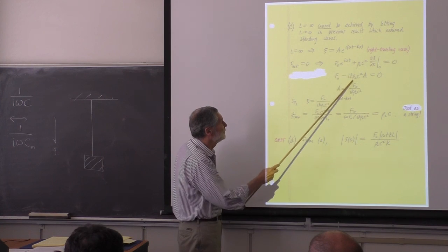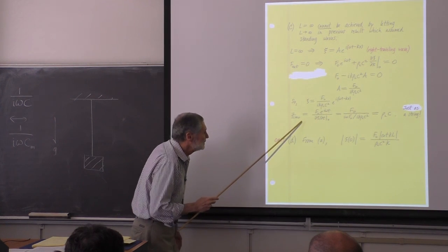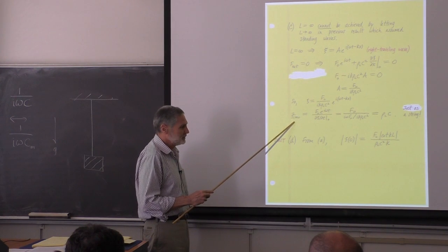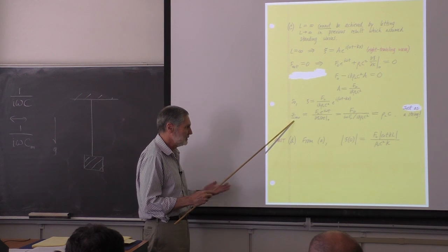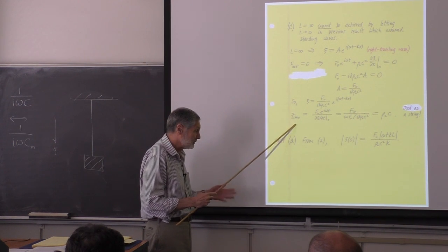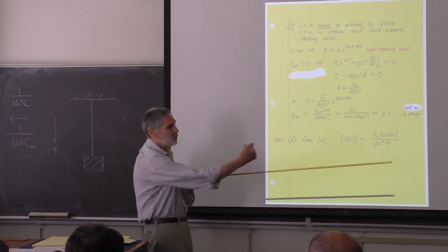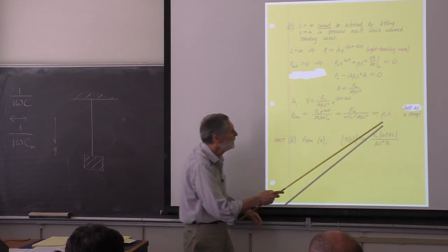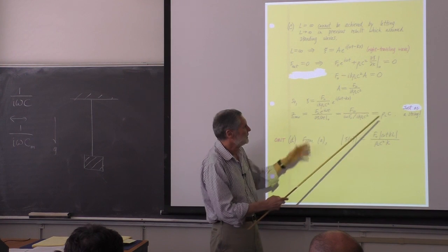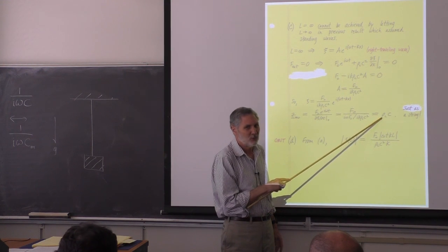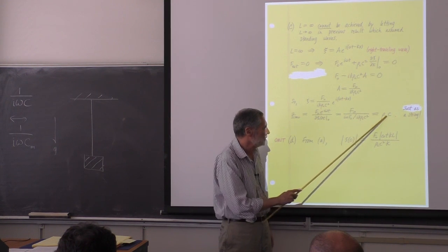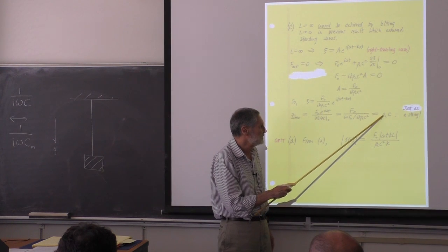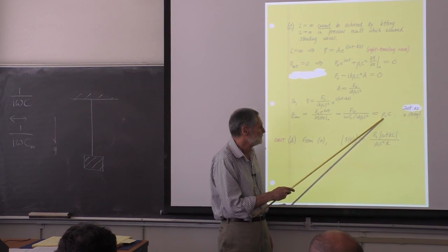Go through what we did before, and what you're going to find is the input impedance, the impedance seen by the drive for this case where there are no waves coming back. It's purely resistive. That energy goes and never comes back. So it's very different than when you have it terminated. And it's rho L c. The mistake I made was thinking it was rho c. This is the mass per unit length of the bar.